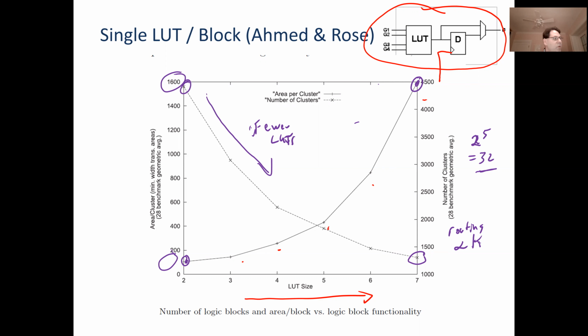So I have to build more routing input ports. If you go back to the first order analysis we did of W, we said W is proportional to lambda R bar over 2. R bar is the thing that's really hard to estimate there. How far does the average signal get routed? But basically lambda is the number of inputs.